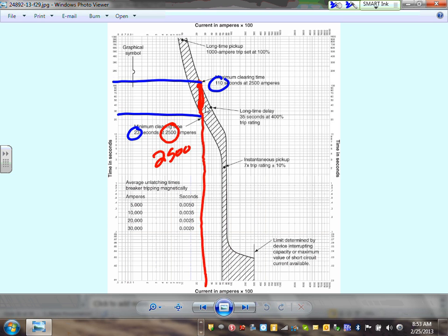The manufacturer will guarantee you that it will open. But they don't know exactly because you're dealing with mechanics, right? Depending on the situation, it could open, but within that gap, the circuit breaker will trip. Any comments, guys? Any questions? It's possible for it to open right at the first one? Yes. So that's where they call it minimum clearing time and maximum clearing time. Minimum needs this amount of time. Maximum, it could take up to 110, but somewhere in between, it is guaranteed that you'll open.